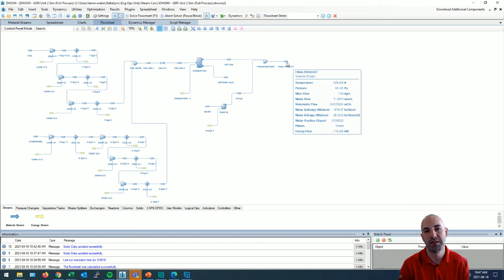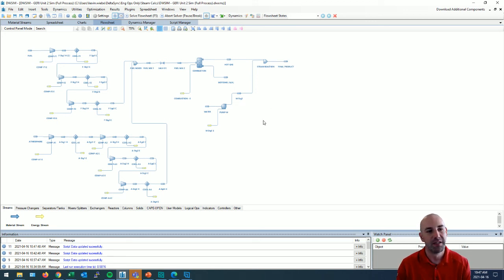And the issue with that is the higher the steam quality you get to, the fewer solids you're going to want to have in your water stream, because the water that's remaining is what's carrying your solids downhole. So at some point you're going to reach that magical number where the water is just not going to handle excess solids in it. This is a high-level overview of what our process is.